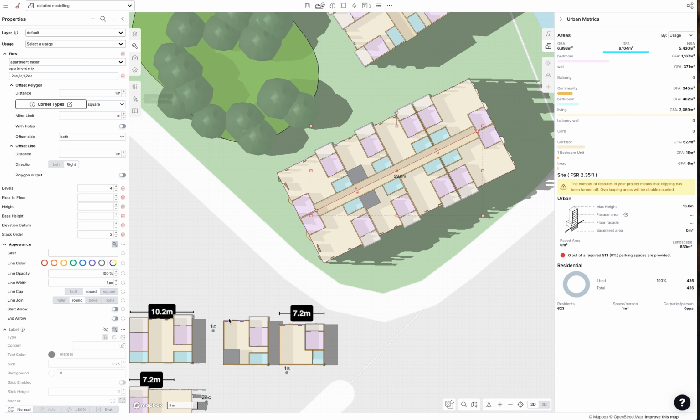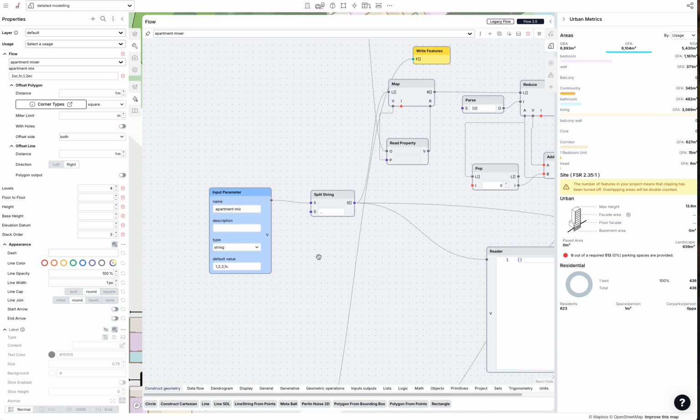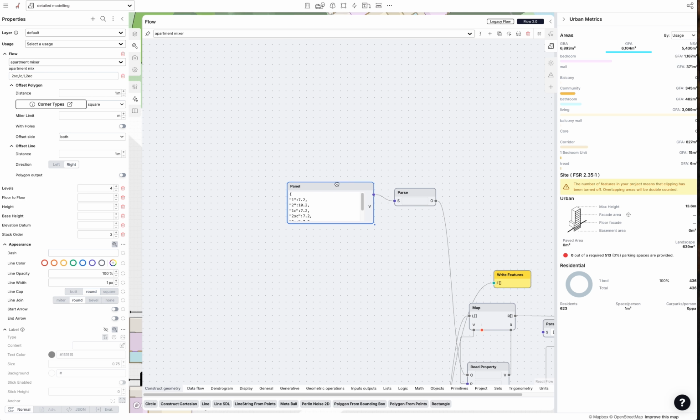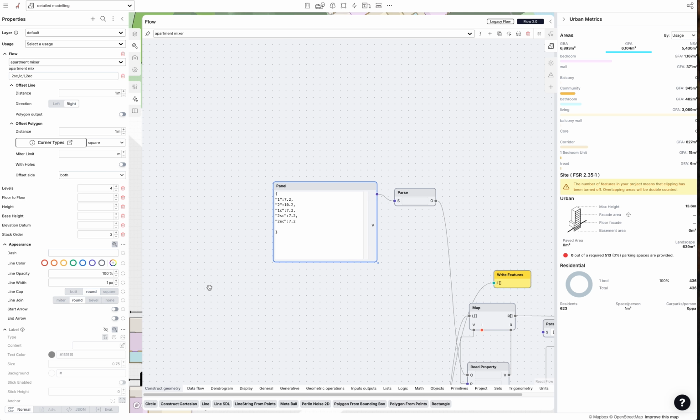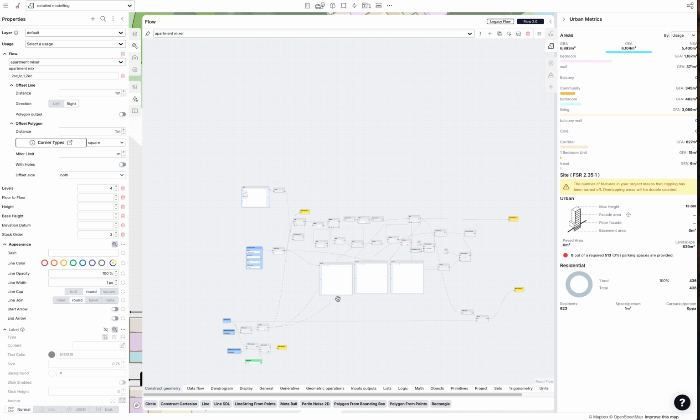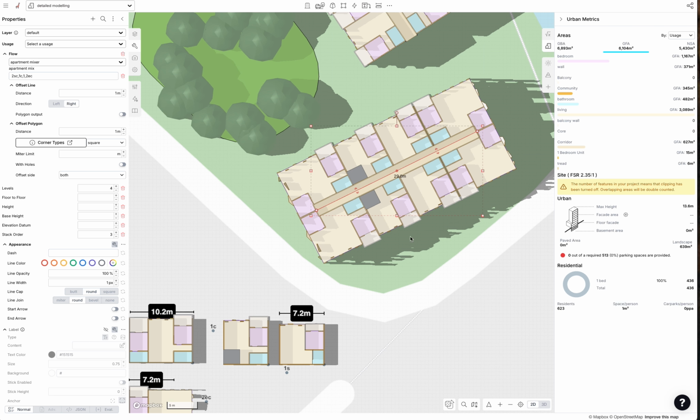And the way that we reference 1S into this flow is we need to add 1S to the data dictionary. And then we can just place it using the inputs, the apartment mix input. So you can see I've got 1, 2, 1C, 2SC, that's 2 start cap, 2 end cap. And now we have 1S for shallow, and that is 7.2 meters wide. So this dictionary is the name of the apartment plus its width, because it's its width that determines its logical placement.